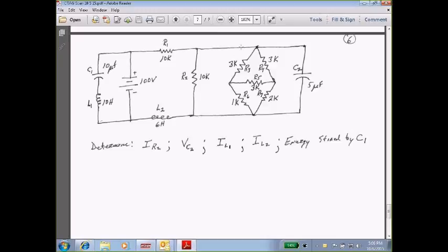So to find I2, we put the 2.2K on top, divided by 2.2K plus the 10K, times 8.5 milliamps. And I come up with, again, about 1.5 milliamps. So I for R2, which is one of the things we're looking for, would be 1.5 milliamps.